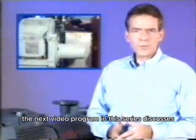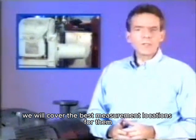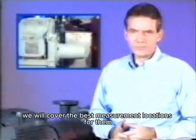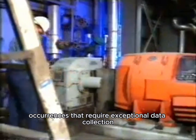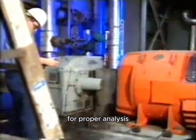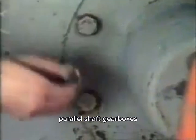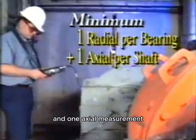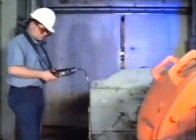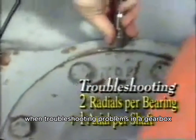Although the next video program in this series discusses gearboxes in depth, here we will cover the best measurement locations for them. Gearboxes have high-frequency occurrences that require exceptional data collection for proper analysis. Routine surveys for single reduction parallel shaft gearboxes require a minimum of 1 radial and 1 axial measurement at each bearing location. Use 2 radial measurements when troubleshooting problems in a gearbox.